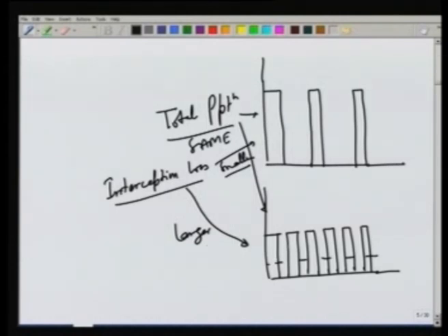In this second event the total interception loss will be 6 times the interception loss for a single storm, while here it will be only 3 times. So, the interception loss will be much higher if we have more frequent storms for the same amount of precipitation.